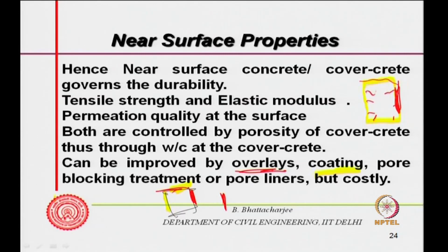Some of them react with the substrate to block the pore. Some act at the boundary of the capillary, react or get adsorbed there, and in the process they change the contact angle of water inside. Since most of the ingress is through water, it will not allow water to come in. So these pore liners, pore blocking treatments, are actually waterproofing treatments, and if water does not go in, then obviously durability will be enhanced.